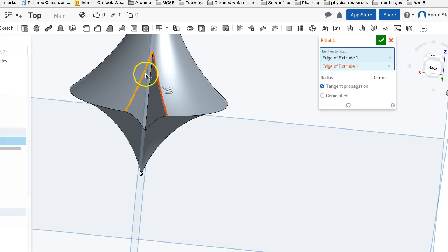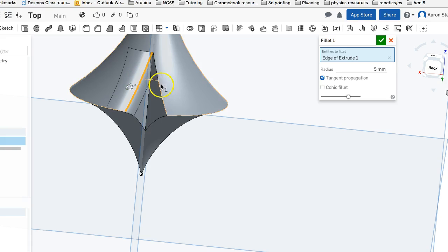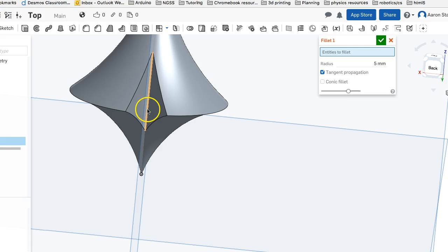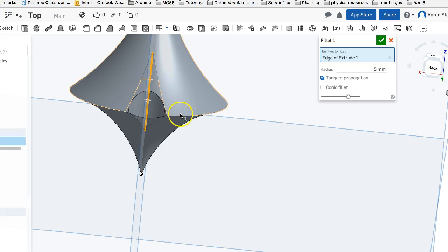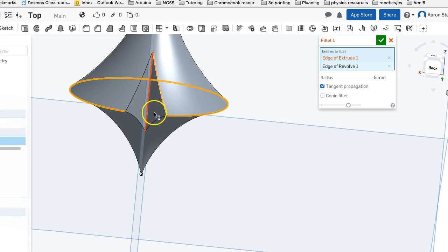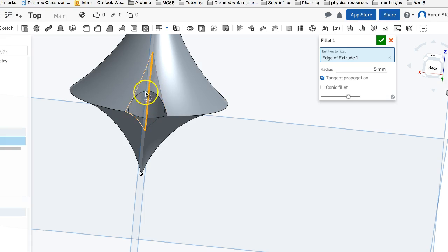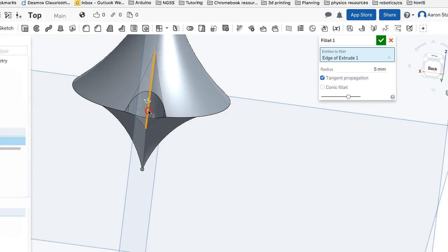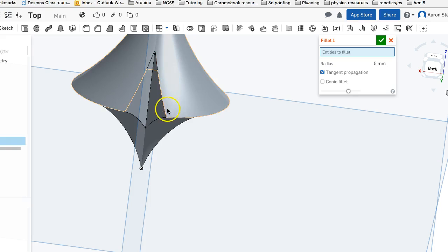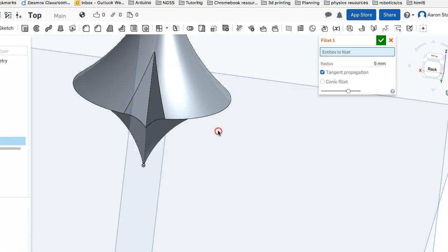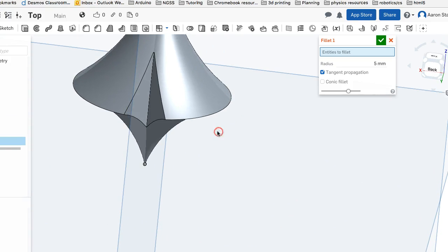It doesn't like it when these fillets intersect each other, so we'll add one here, and then we'll just add one. Yeah, we'll just do the one right here. Nope, that's not what I want. We just won't even worry about it because it's not working out. I gotta learn more about those. So now what we can do, if we added a fillet, we could pattern that fillet.